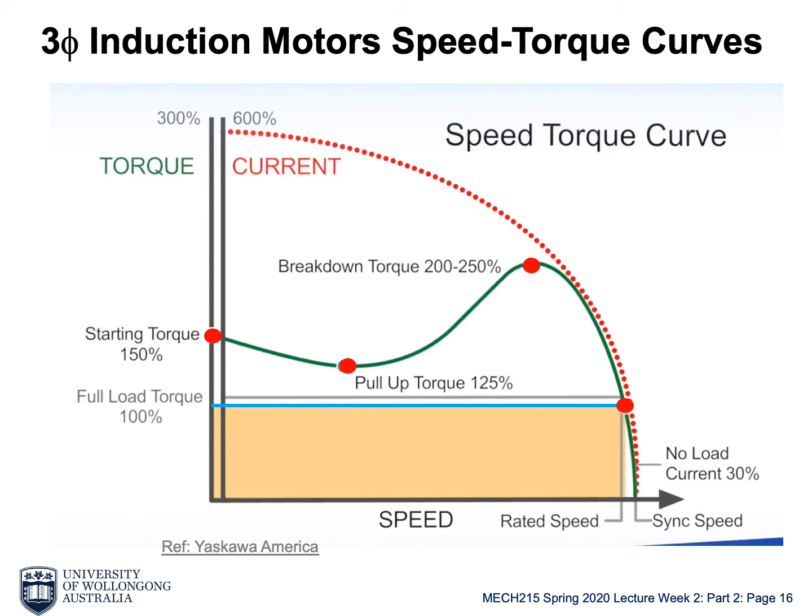So this period of speeding up needs to be short enough so the total motor heat generated, the heat, is equal to I squared multiplied by R. R is the resistance of the coil. So that needs to be fast enough. So the energy, the heat generated during this speed up is not too much, so the motor will not get too hot and get damaged.